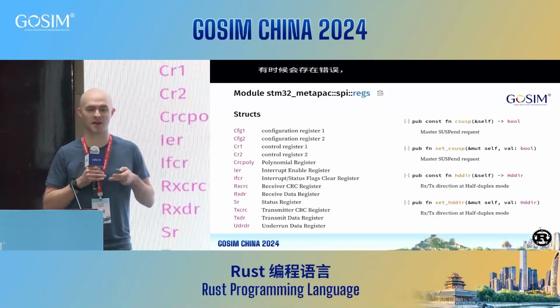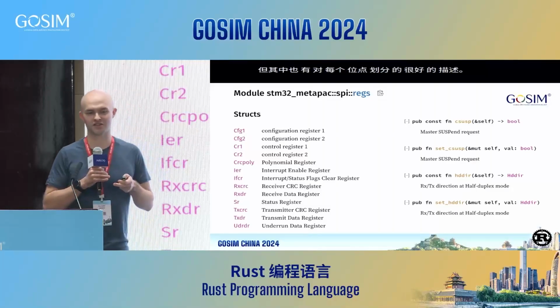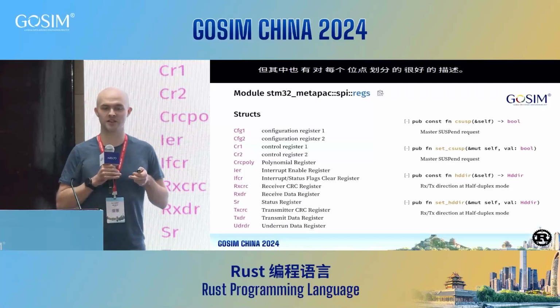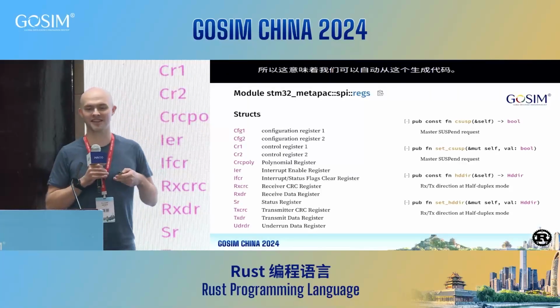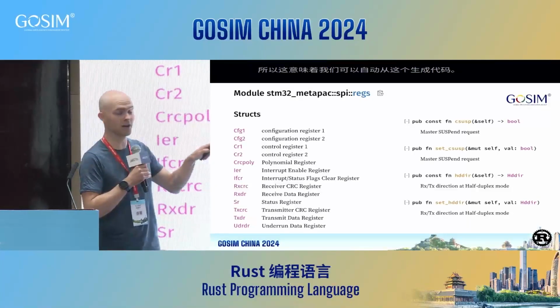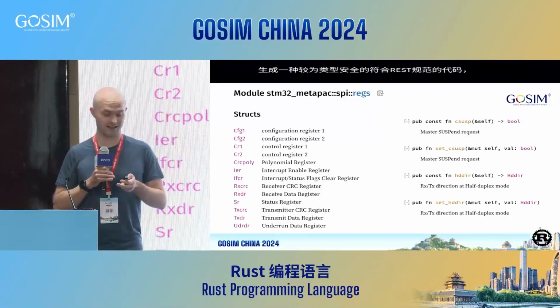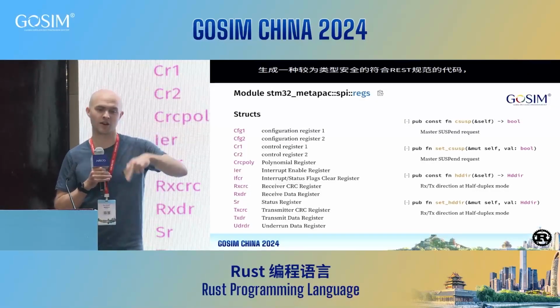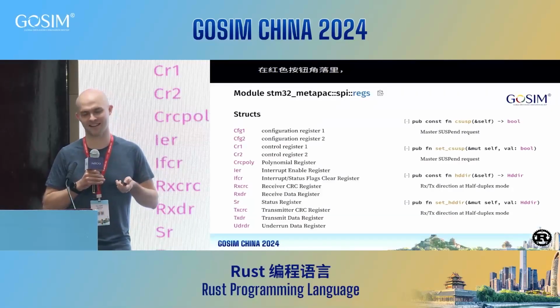That means we can generate code automatically from this. We use the macro system and maybe some other utilities to generate compliant Rust code that's somewhat type safe. For example, in the bottom right corner you can see that you can set a strongly typed enum to a register or part of a register. Internally, there's actually code doing bit masks and those kinds of things.